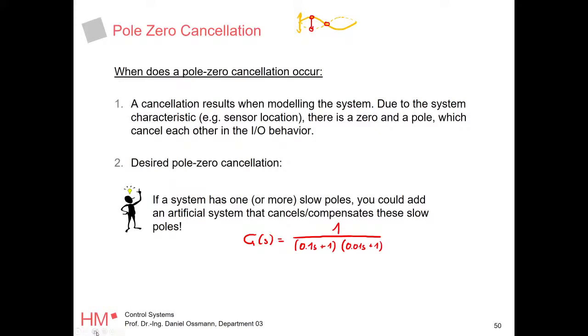And now you're saying, okay, what I've learned so far is that this eigenmode kind of dominates my response. So my response of that system will take some time. It will take 0.1 seconds times 3 to reach 95%. The other one with 0.01 seconds is pretty fast. This disappears pretty fast. So my system is dominated by this 0.1 second eigenmode. This guy is the reason why my espresso machine needs so long to heat up.